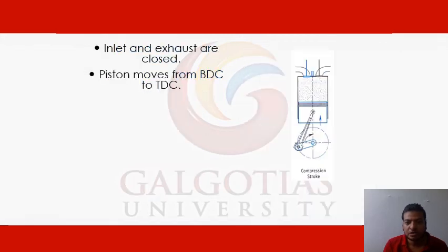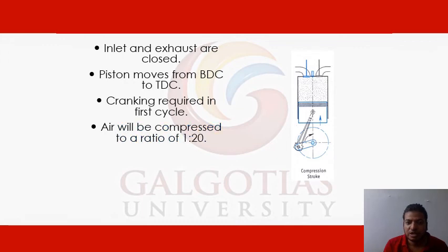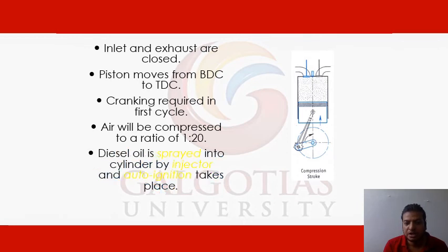So the inlet and exhaust valves are closed. The piston moves from bottom dead center to top dead center. Cranking is required in the first cycle. Air will be compressed to a ratio of 1 to 20. Diesel oil is sprayed into the cylinder by the injector and auto ignition takes place. This is talking about the diesel engine.